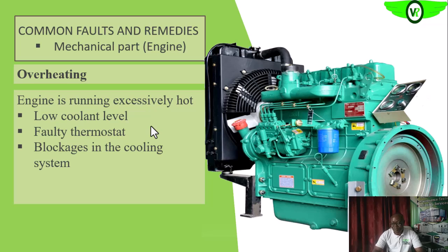So if they are completely blocked by deposit, it means that water will not flow through those passages. And if water does not go through them, from that point forward, all will be overheated, and that will show up as overheating on the engine. So we want to be very careful with that.